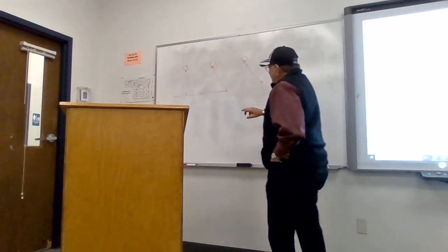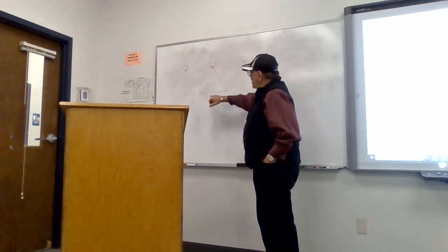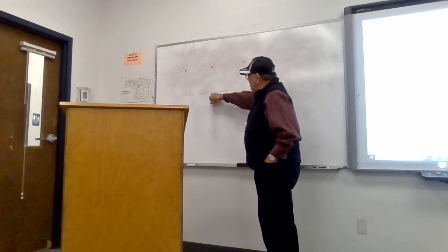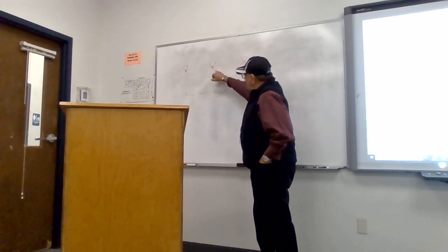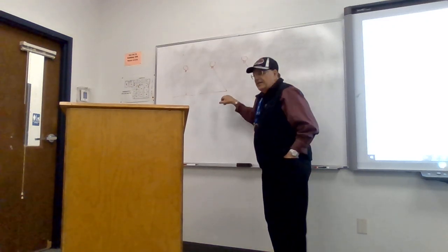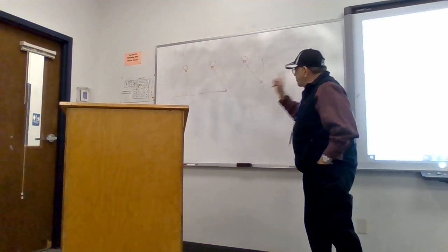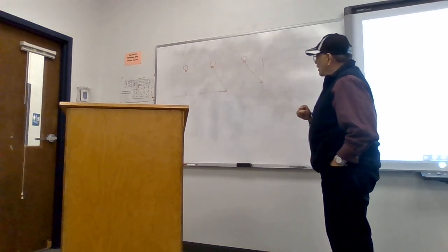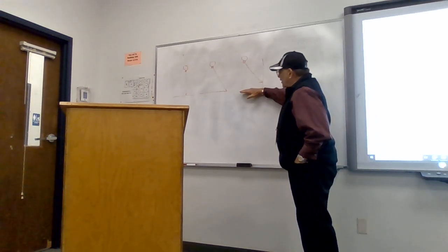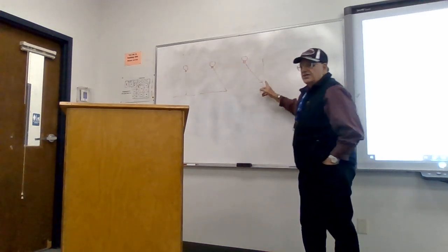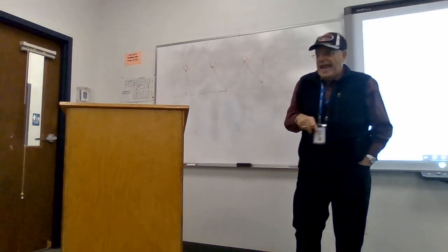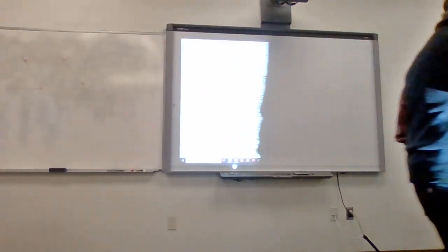Then we're going to say, I don't want to know about what's directly under the light bulb. I want to know from this angle what the foot candles might be in this position. And the third measurement is, instead of the flat plane here, we're going to look at the vertical plane and say, what are the foot candles on the vertical plane?